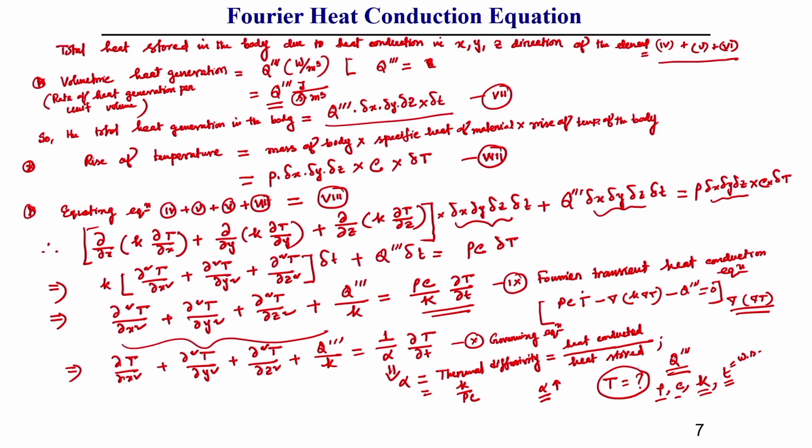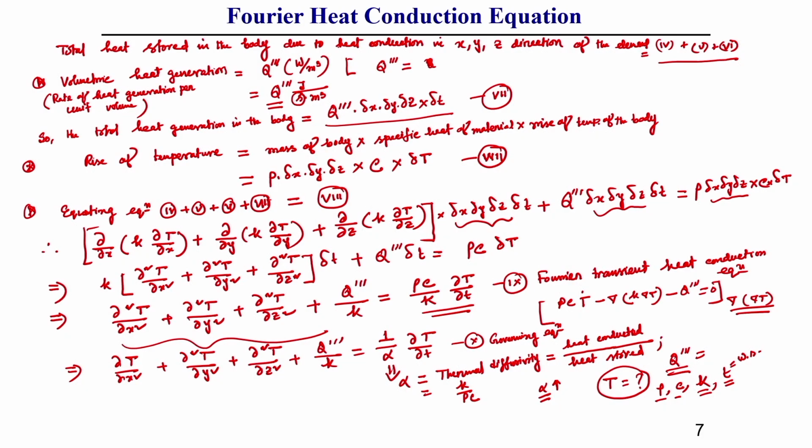And Q generally depends on arc energy, as well as arc heat source shape and size. How is this Q calculated? Q is a function of the coordinate system as well as voltage, current, and efficiency also. This you should keep in mind.